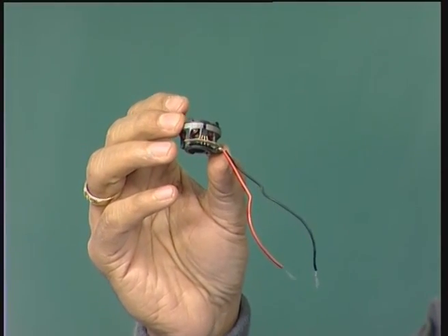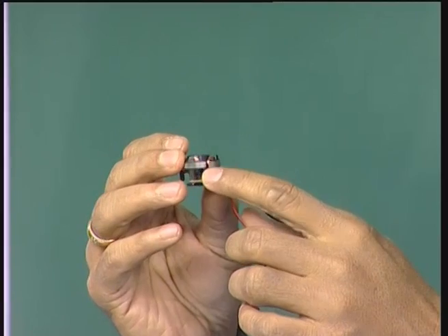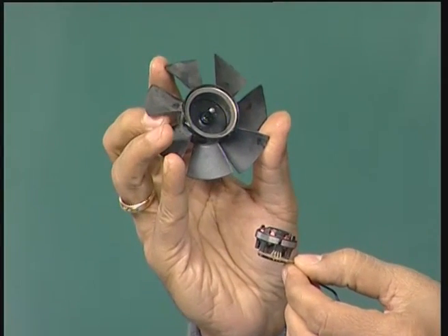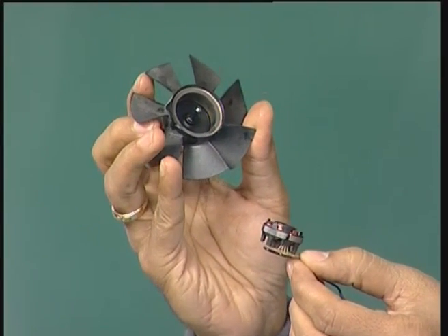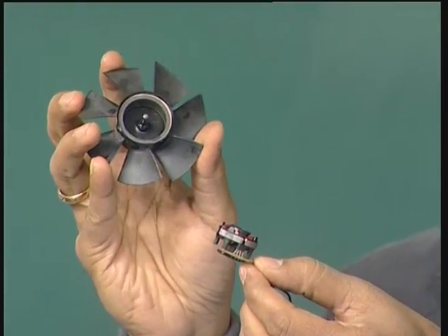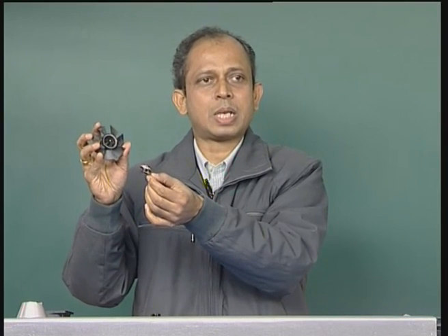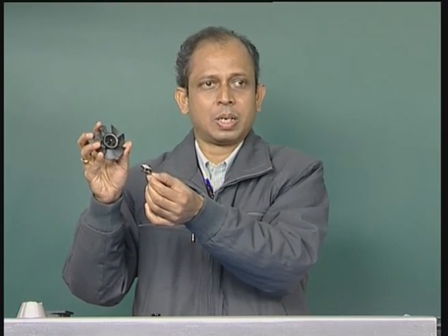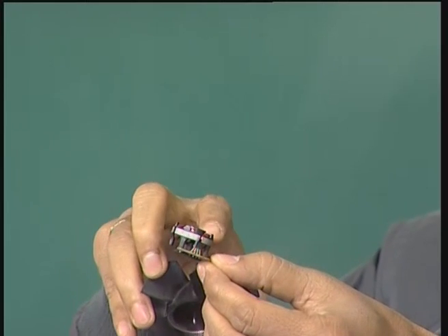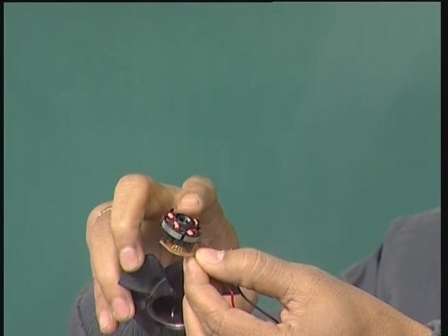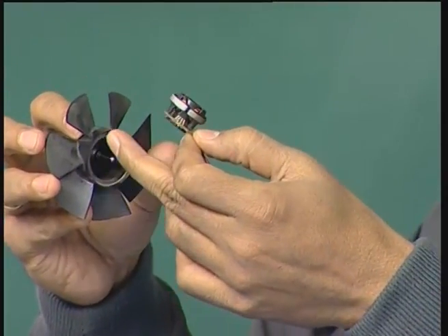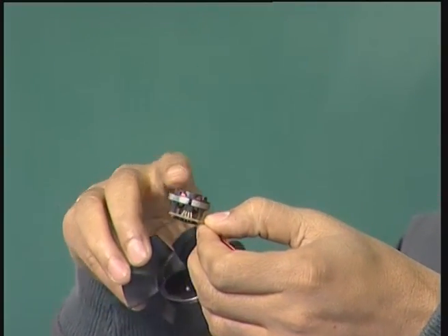Since we have the DC power supply, the DC power supply is given here, so we have a switch, and then the rotor position is sensed here by Hall effect sensors. The rotor position can be sensed by an optical encoder. This can also be sensed by Hall effect sensors, because Hall effect sensors are the sensors which can detect the field position or the position of the flux lines. So, here the Hall sensors are mounted on the stator, and they sense the position of the magnets in the rotor, and accordingly the windings are switched on and off.